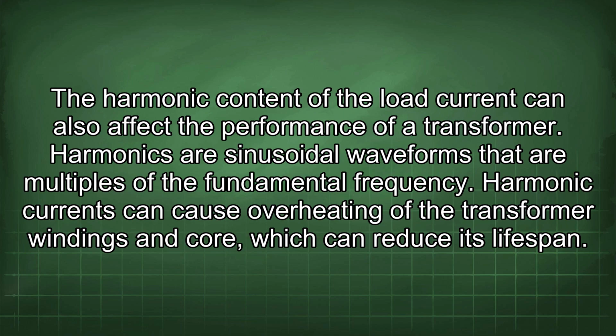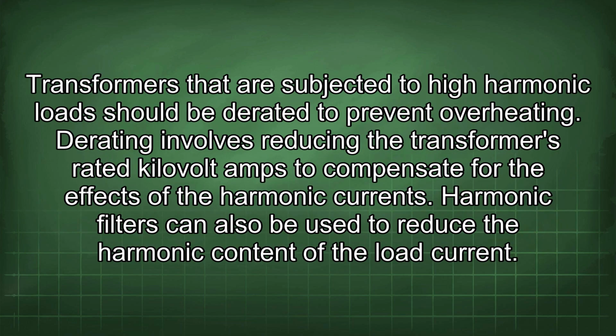The harmonic content of the load current can also affect the performance of a transformer. Harmonics are sinusoidal waveforms that are multiples of the fundamental frequency. Harmonic currents can cause overheating of the transformer windings and core, which can reduce its lifespan. Transformers that are subjected to high harmonic load should be derated to prevent overheating. Derating involves reducing the transformer's rated kilovolt amps to compensate for the effects of the harmonic currents.